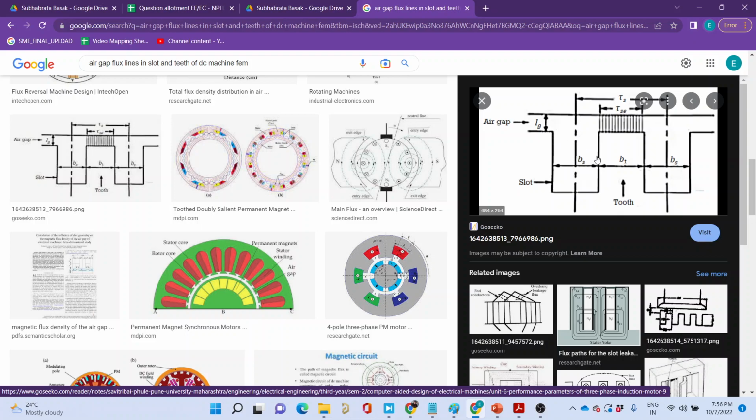You take the direction of the motion, and figure out accordingly what would be the direction of the current. And because of that conductors, you draw the flux lines of only these conductors. Flux lines produced only by the armature current, which is placed in these slots. And in the third picture, you show me the resultant flux that is being produced.